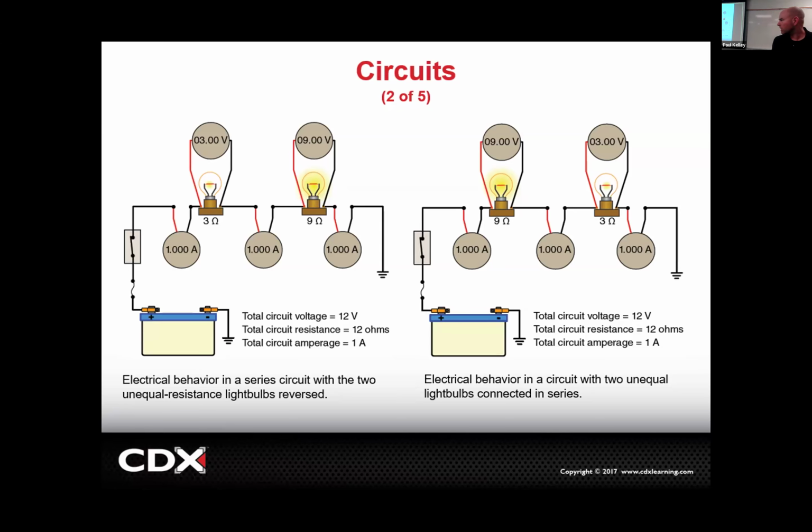Make sense? Look at the first bulb. The first bulb is dim. Can you tell it's just barely lit? And the second bulb is consuming all the voltage, so it's much brighter, right? It's getting paid a lot more. What if this wasn't a bulb and it was just that unwanted dirty resistance? What would happen to the first bulb? It would be dim, but you'd have no idea why.